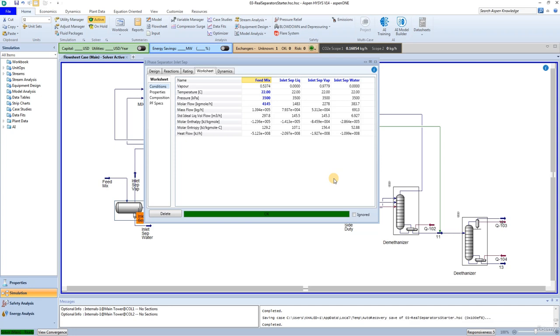Finally, based on the separation extent from the previous step, the program calculates the effect of any installed secondary separation device on the liquid carryover into the vapor product. This is only available in the horizontal and the ProSeparator correlations.